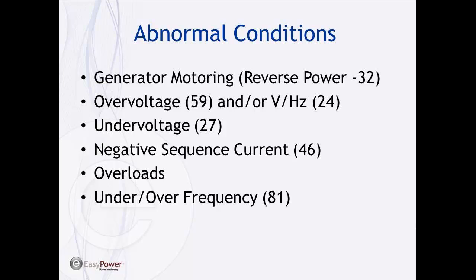When you get into over and under frequency, sometimes the interconnection requirements that are imposed on you by the utility or the grid will become the dominant issue there to deal with. So there will be some overlap between the generator protection and your interconnection requirements.